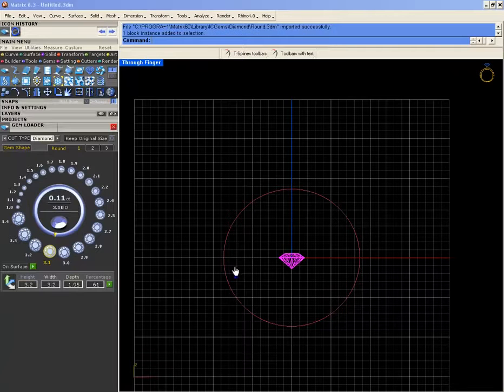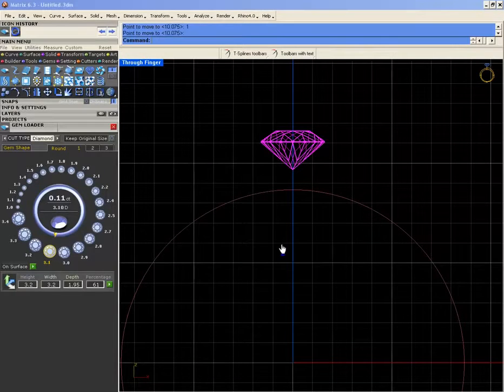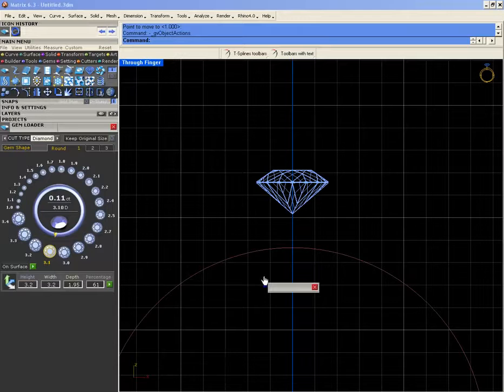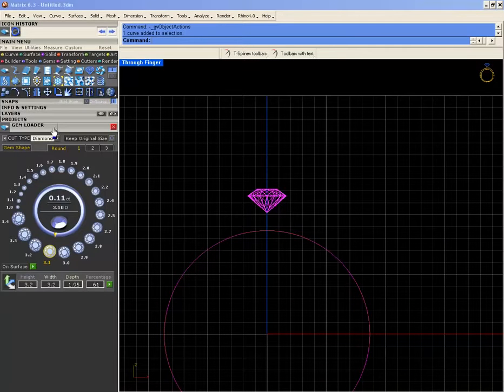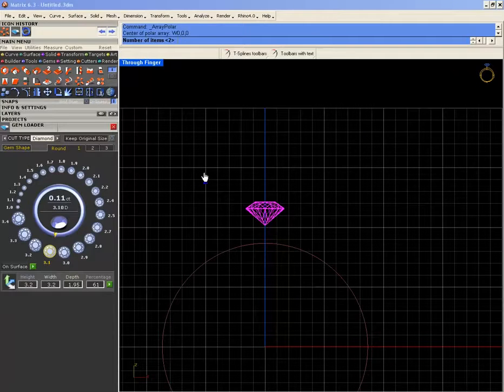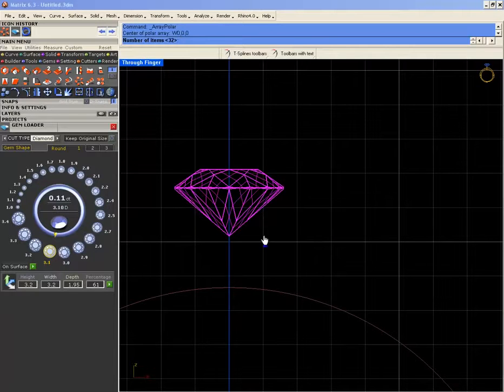This is okay. Move it here 1 mm. Let's move it more. 0.5. Right now I'm gonna make an array with the minimum gap of 0.2 mm. 32. Let's try with 32. It's too much. F4, 28, and still intersecting. F4, 22.